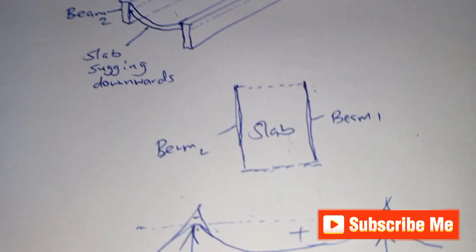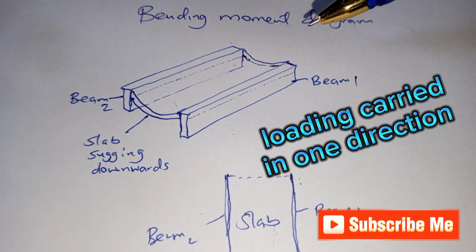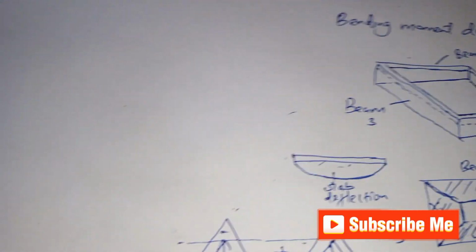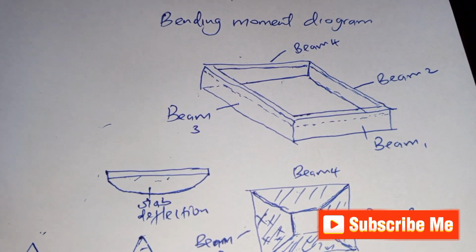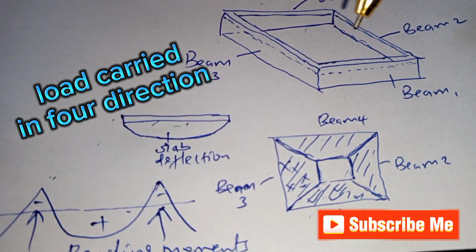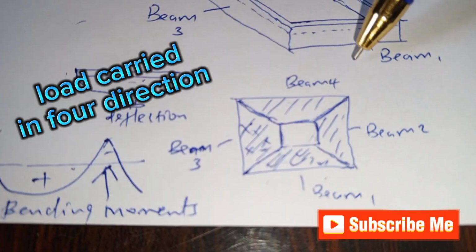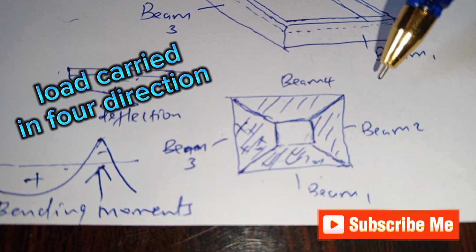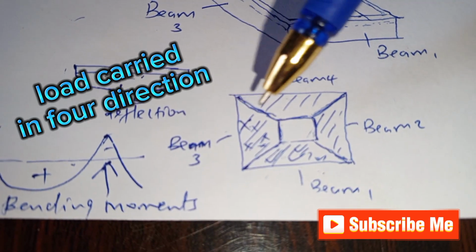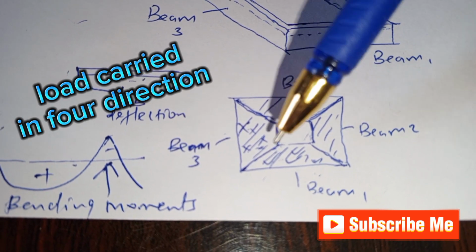Now, for a one-way spanning slab, the load is carried along one direction. Unlike a two-way spanning slab, where the load is carried in four directions. What do I mean that the load is carried in four directions? Using our 2D illustration here, we have beam 1, beam 2, beam 3, and beam 4. This is our 2D illustration showing the beams, and in between is the slab.